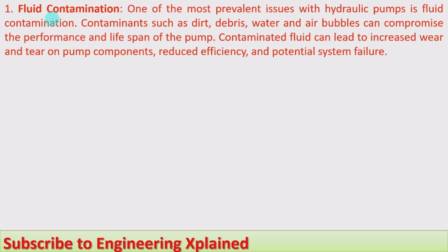The first one is fluid contamination. One of the most prevalent issues with hydraulic pumps is fluid contamination. Contaminants such as dirt, debris, water, and air bubbles can compromise the performance and lifespan of the pump. Contaminated fluid can lead to increased wear and tear on pump components, reduced efficiency, and potential system failure.